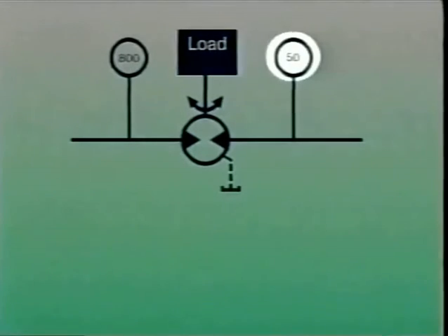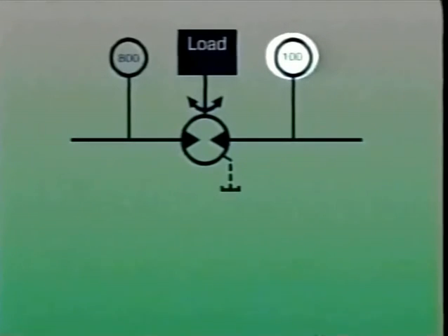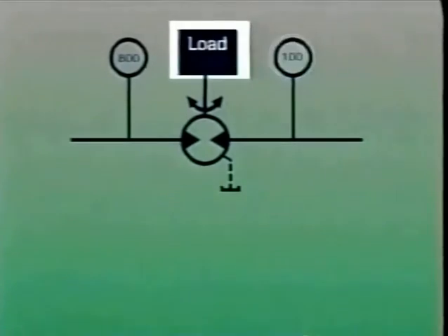Changes in outlet pressure occur in all industrial systems because there is always some back pressure present in the tank line. Usually, back pressure is at least 50 psi, and frequently it's as much as 100 psi or more. In this system, 100 psi back pressure prevents the motor from moving the load because back pressure attempts to turn the motor in the opposite direction.